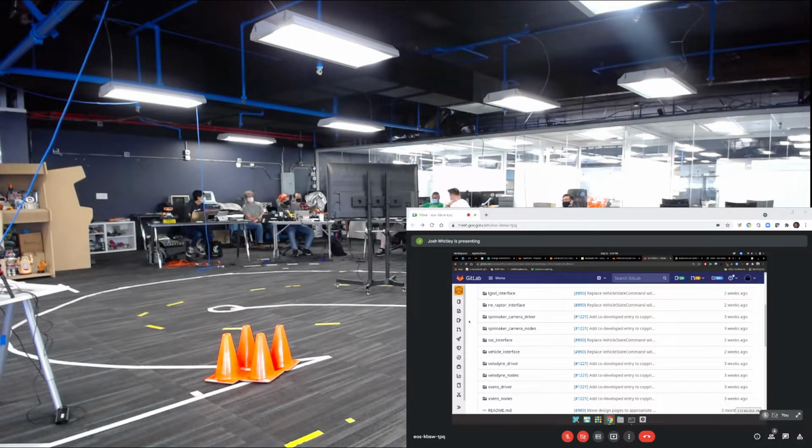Yes. But in this case, they have like a vehicle interface. So if you were doing your own drive-by-wire system, you're going to have a ROS 2 driver, which directly interfaces with the hardware and turns that all into ROS messages, right? The vehicle interface is like Autoware's driver to your driver. It takes Autoware specific messages and then turns them into your drive-by-wire system messages, and vice versa.